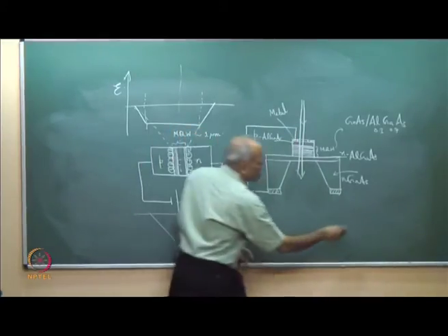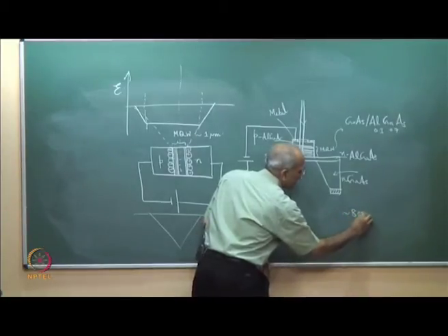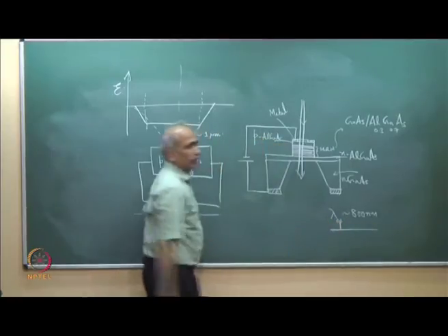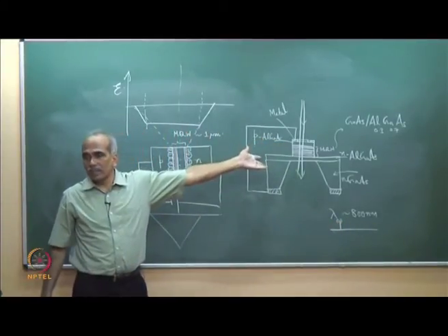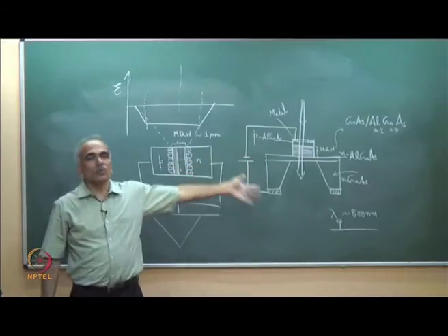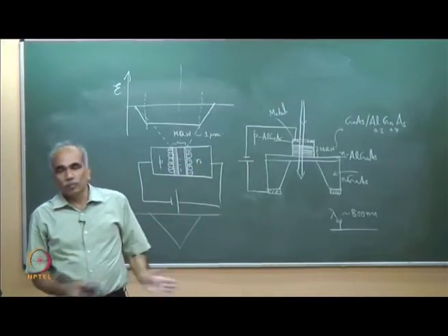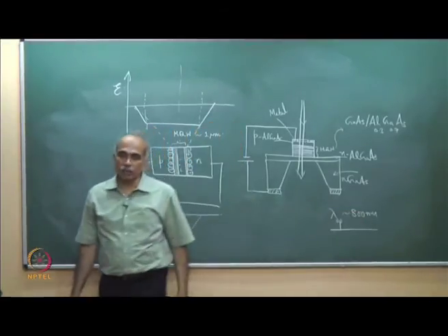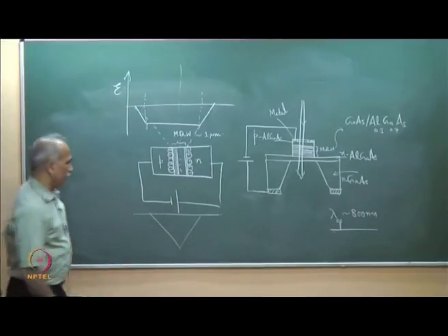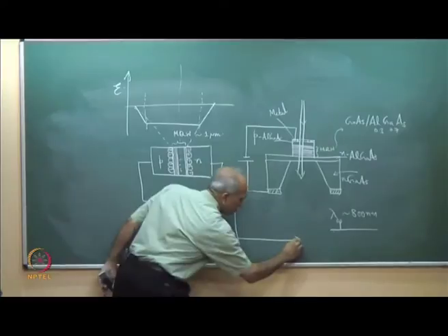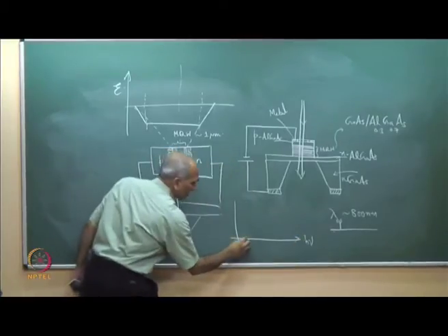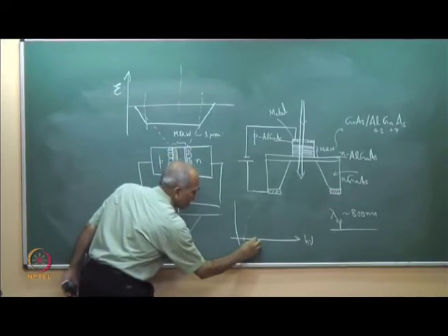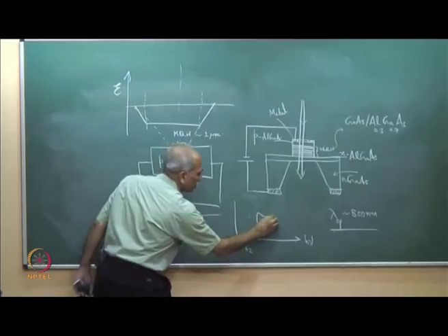This is for operation around 800 nanometer, because the material is gallium arsenide, aluminum gallium arsenide. The band gap is about 1.42 for gallium arsenide. So, 1.44, 1.45 will give you approximately 800 nanometer as the operating wavelength. I hope it is clear. You recall that for gallium arsenide bulk it was here, this is 1.42, and then for the quantum well it was here.